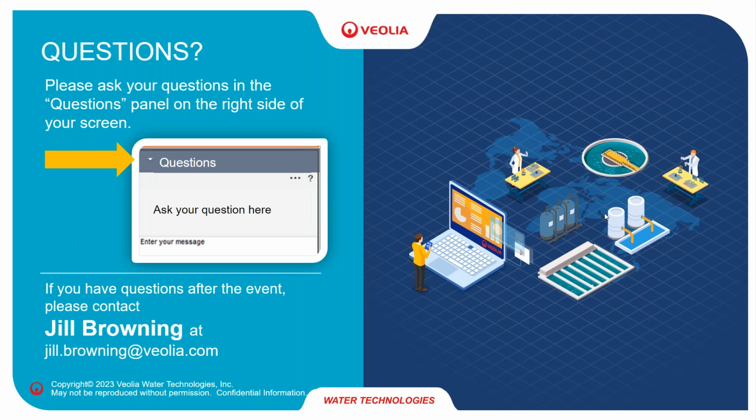Conventional RO is generally limited to about 230% calcium sulfate with antiscalants. We feel we could go a little higher, probably around 400%, pretty easily. Beyond that, we feel we could even do maybe about 600% calcium sulfate, but you need to do some piloting validation. So to answer the question, we have to look at all the chemistry,